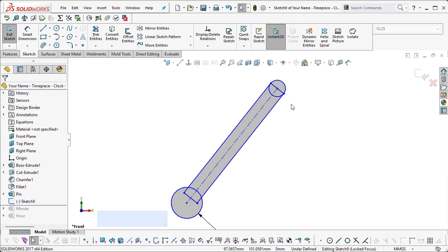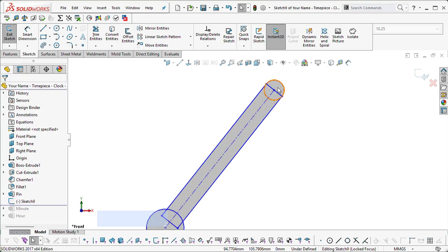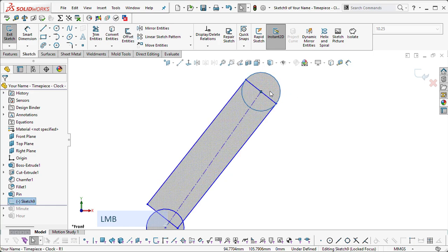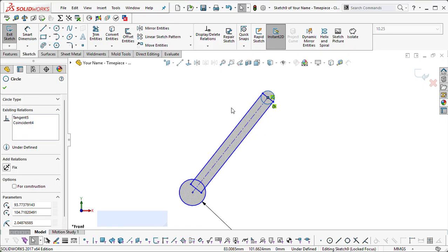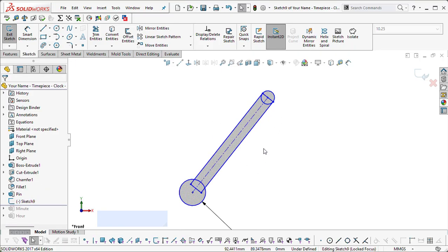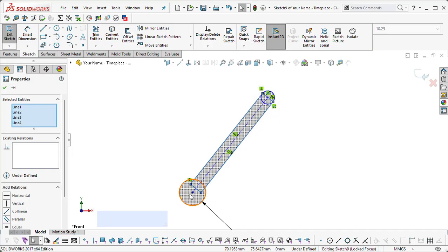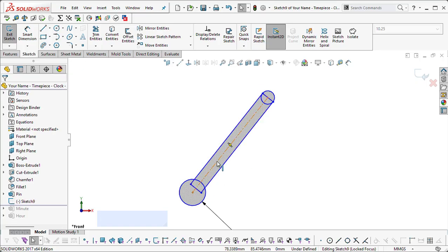Okay, so that was the point of what I did in class. Watch what happens when I try and move the circle around. It's going to squeeze the whole thing. So until I've properly defined this sketch using relations, this rectangle is not linked to that one nor to that line.